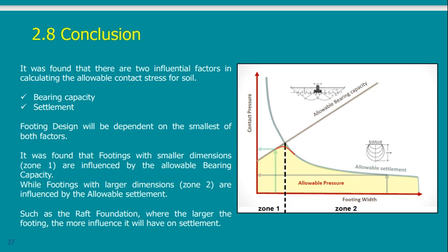When I go to the office and I want to use your report, I will start, say, by assuming that the breadth of the footing is 2 meters. I go with the 2 meters up, I meet here this curve for the allowable, I get the contact pressure. I design based on this, and I get the dimensions of the footing. If the dimension is similar to the one that I assumed, then I'm okay.